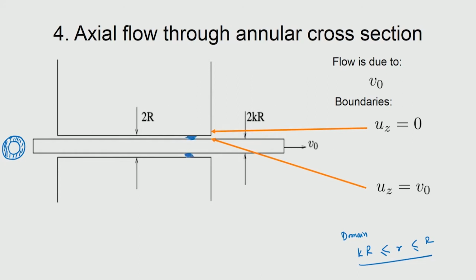So, it is still in the axial direction only. So, boundary conditions will be as follows. The liquid is actually flowing because the inner shaft is being pulled out at a velocity V naught, and because the liquid would get stuck to both the walls because of the no slip condition, there will be a shearing of the liquid. So, velocity gradients are being set up.